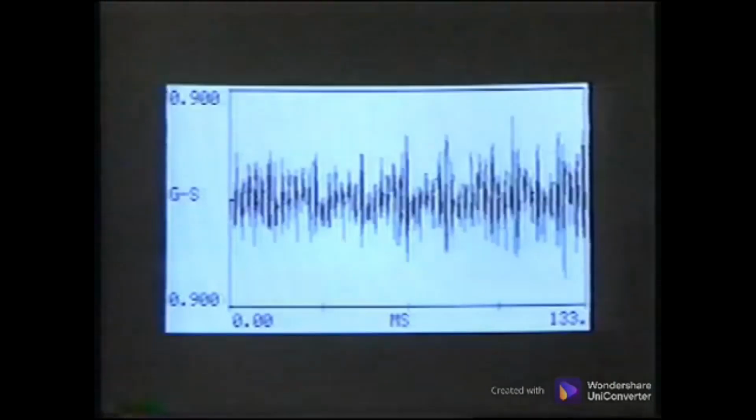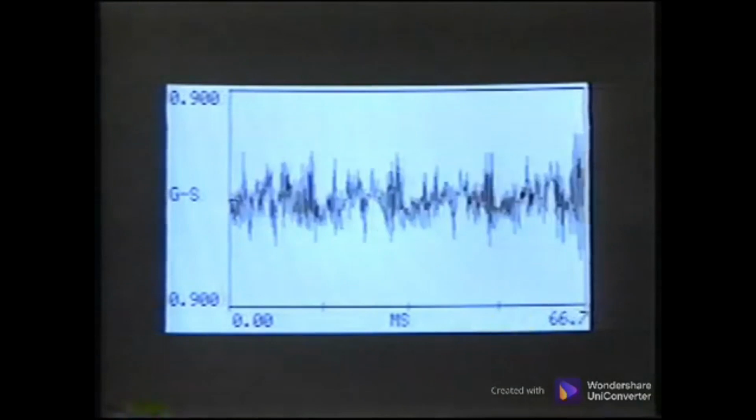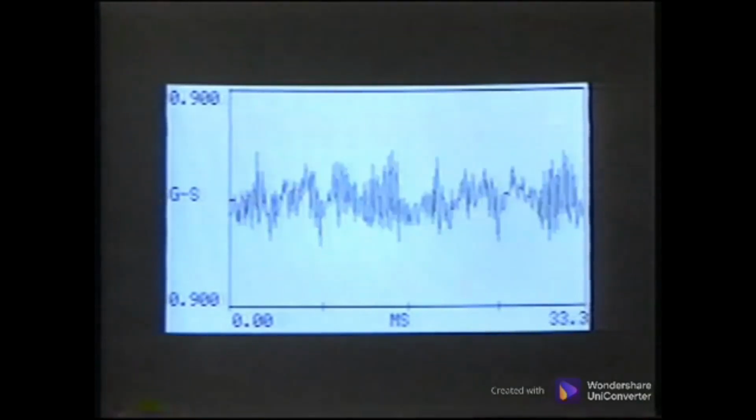With 3000 hertz as the maximum frequency, the time window in the waveform is only 133 milliseconds or 0.13 seconds. Remember that there are 1024 data points in this waveform. This means there is extreme detail for the 0.13 seconds. However, a short time waveform cannot capture multiple occurrences of low-frequency events spaced even a half second apart.